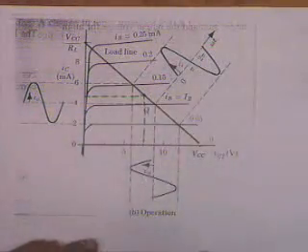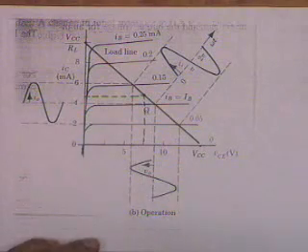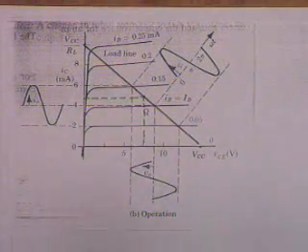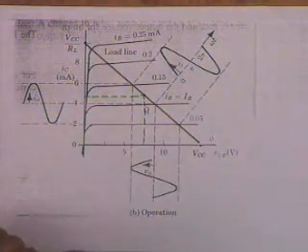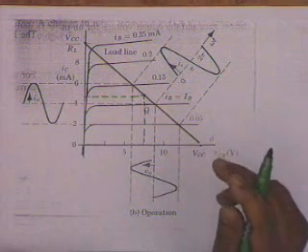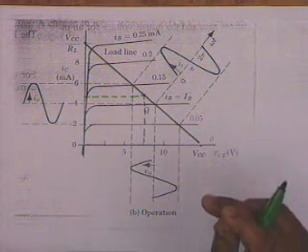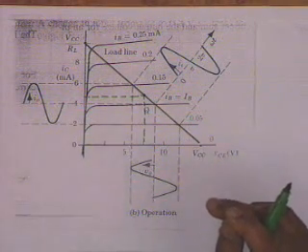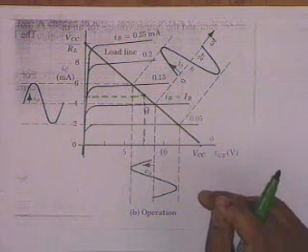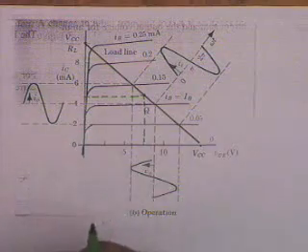Then what is the power dissipation? Five times 7.5, which is 37.5. That is the maximum dissipation allowed in the transistor. Is that okay? Yes, sir. We cannot exceed that. Alright.